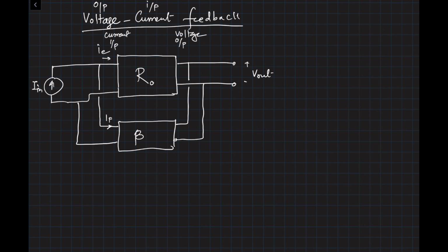So in this particular case, what you would see is V out divided by I in. Originally, it would have been R out, and now it will be R out divided by 1 plus beta times R out, something like that. In the voltage case, we had A0. In the trans resistance amplifier, it will be the R out of the amplifier.